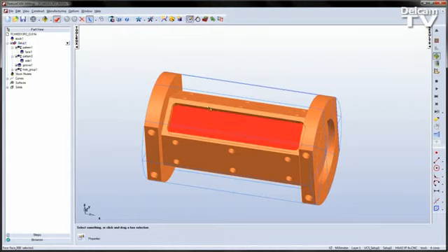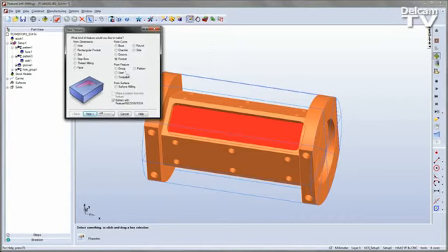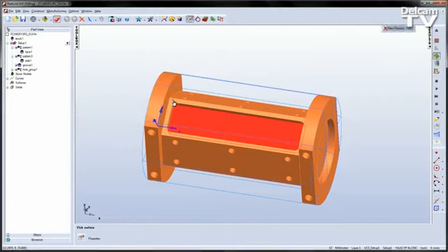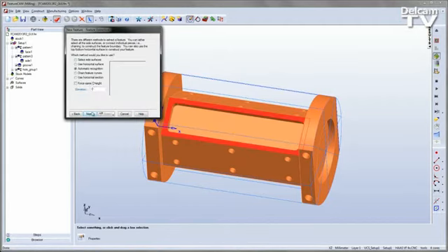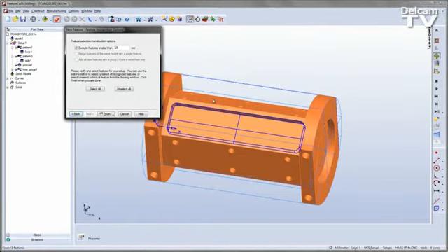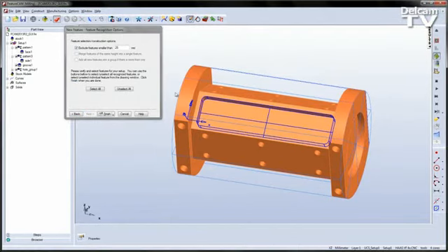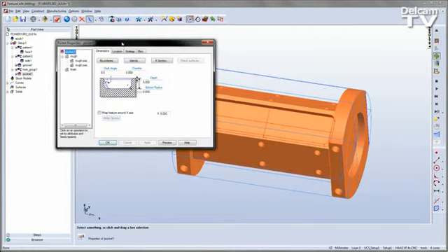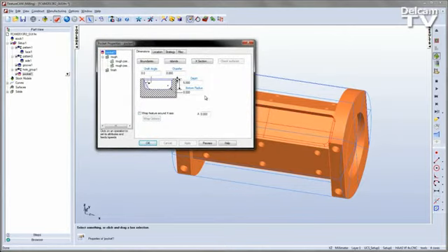I'm now going to create a pocket feature from this orientation, so create a pocket, extract with feature recognition. I'm going to go normal to this surface, and I'll use the automatic recognition to find a pocket. I'm going to select that pocket and say finish, and I now have my typical feature dialog as I would expect.